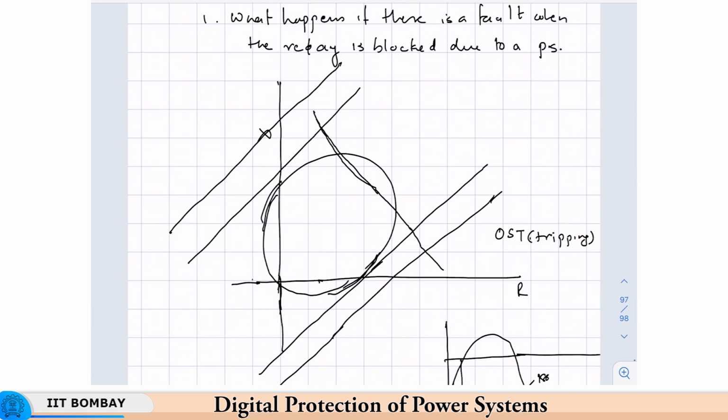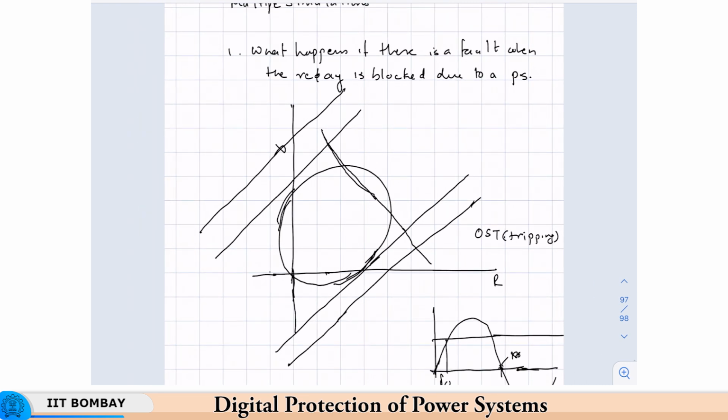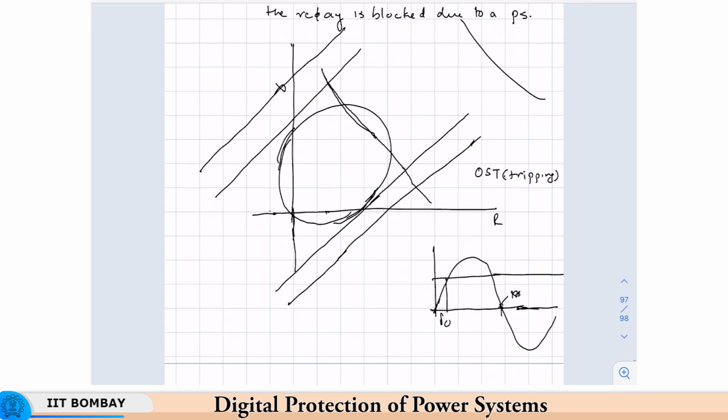Now, just as a word of caution, you could have some swing which is actually very far away, and since these characteristics continue, you have a swing very far away. So, the impedance is very low. So, it does not matter, and to prevent operation here, you have overcurrent relays also.